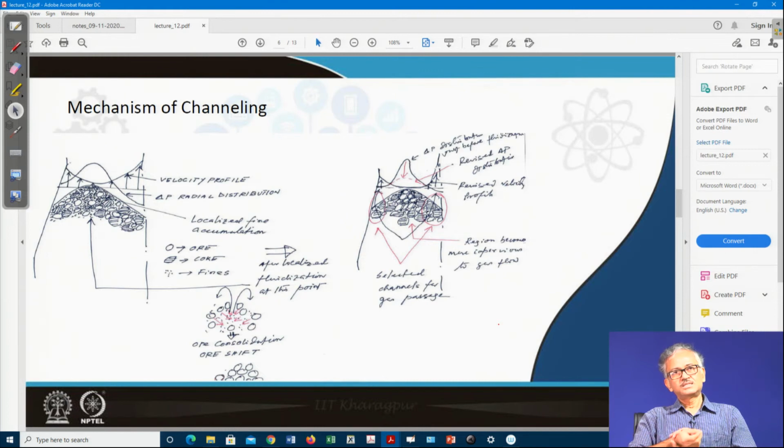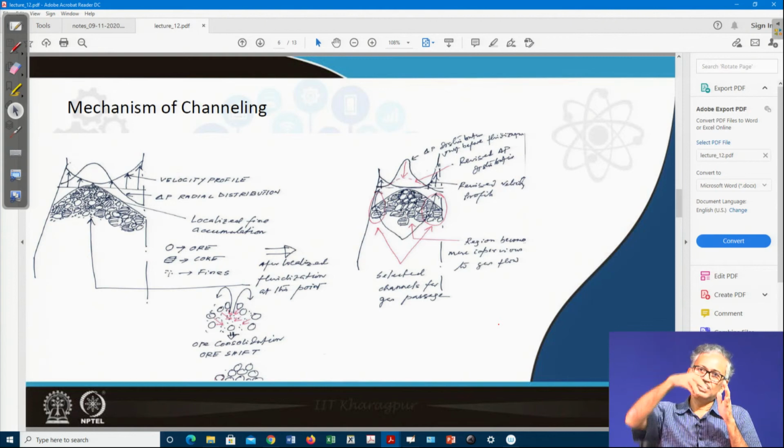So, what is the remedial action? Before it can happen, because you have a lot of underburden probes nowadays in the axial and radial directions, you can easily map the local pressure drop. If you find in some place the pressure drop is increasing, in that case you can change the burden distribution, and in that place you can charge some amount of coke, because now we have bell-less charging. So, wherever you want permeable material you can charge. Coke is more permeable. So, if some place is going to be very impervious, you can charge some amount of coke in that location such that it slowly becomes permeable.